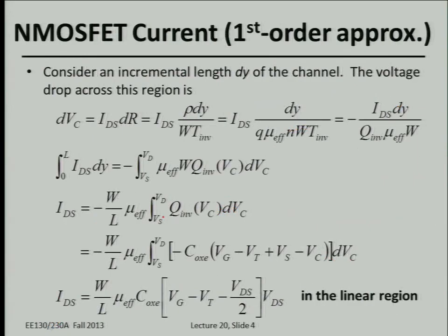Okay, so before we get to the derivation of the drive current, let's analyze a problem by looking into the MOSFET device, with the source and drain, once we form some channel. In that case, the MOSFET itself just looks like a semiconductor bar, right? Once we apply some voltage across it, we are expecting some drift current through it, right?